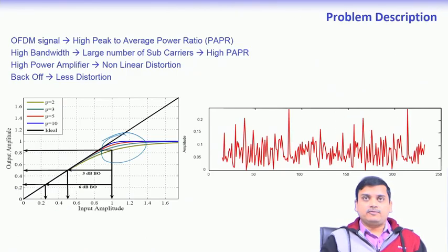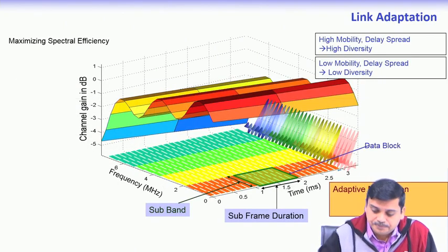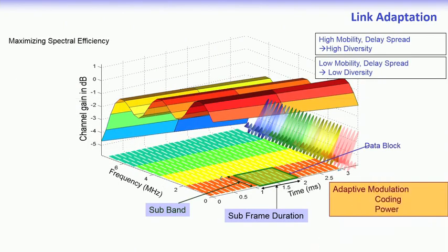Now, another way of seeing it, let's carefully take a look at that. If one of the users is being allocated only one such band of frequencies, right, that means only these few frequencies are going to get non-zero constellation points or symbols. So, for that user, all the other subcarriers would be getting 0 in the symbol value.